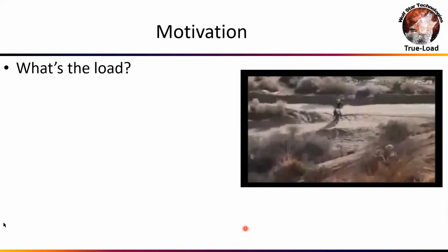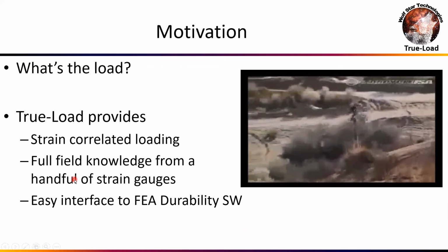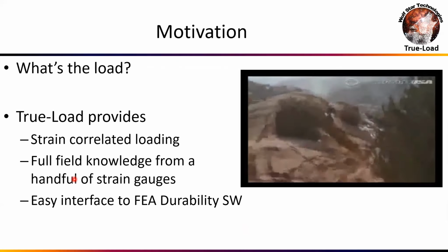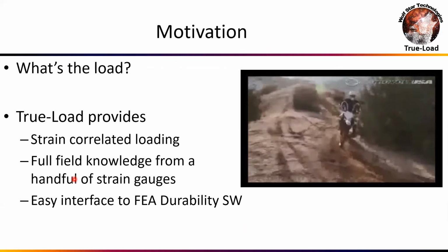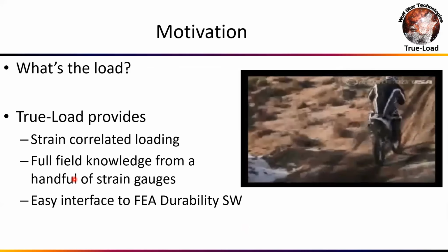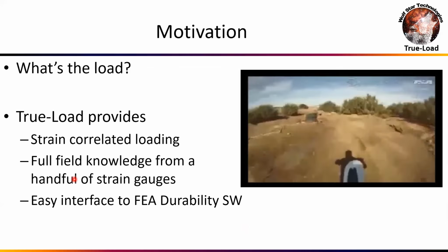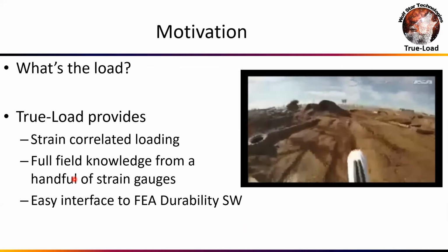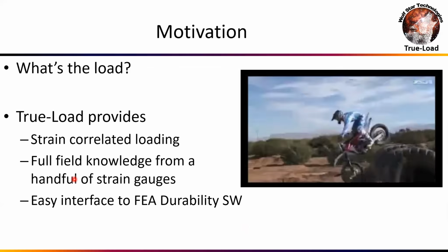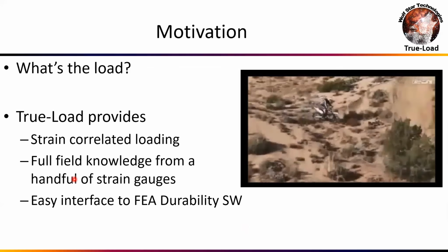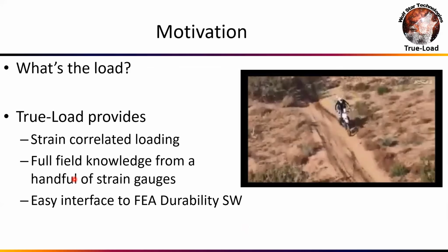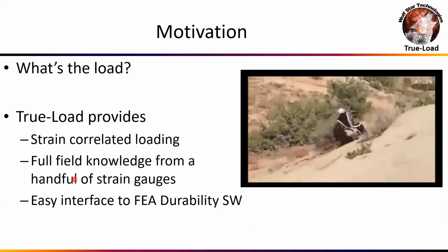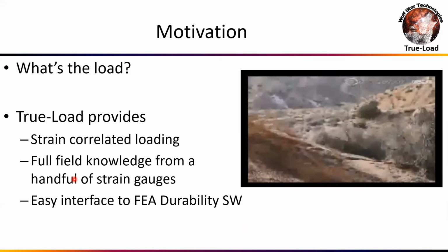Well, what we recognize is that the individual components are basically responding linearly. So we'll place strain gauges on the swing arm, on the frame, on the crankcase, on the handlebars, on the fenders, on the gas tank, on the luggage system. We'll turn the individual subsystems into load measuring devices, and we'll measure the real-time operating loads from these structures, and then use those loads to do design and development and to help you optimize those parts. So that's how you can do the design.